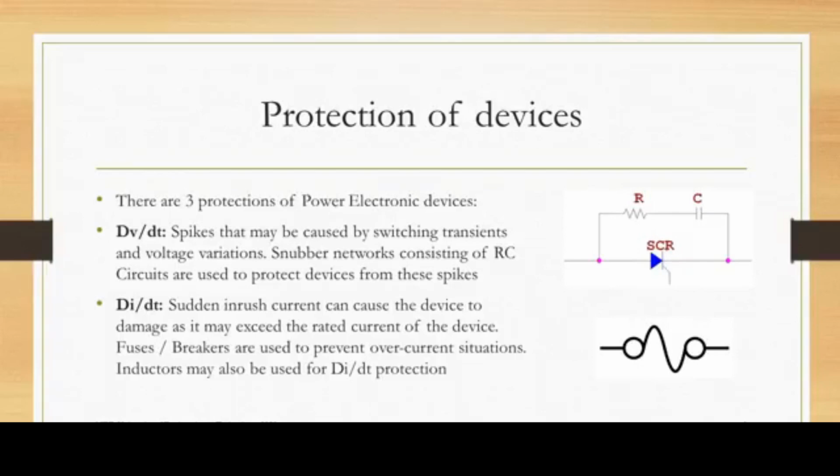A forward polarized snubber is suitable when a thyristor or transistor is connected with an anti-parallel diode. Well, due to the reverse recovery time and recovery current, an amount of energy is trapped in the circuit inductances, and as a result, transient voltage appears across the device. In addition to dV/dt protection, the snubber limits the peak transient voltage across the device.